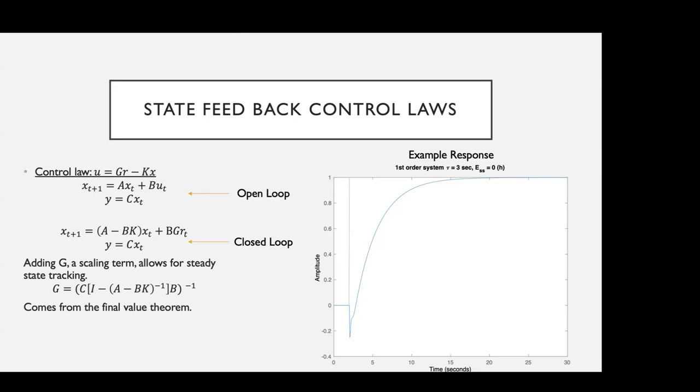If you choose a pole placement, that characterizes overshoot, response time, settling time. There are all those things that you can design for. So if I say, I want it to respond in 10 seconds and have an overshoot of less than 2%, there are formulas to calculate what the pole should be to enforce that. So that's kind of like performance characteristics, I guess. I don't know if that's to the degree that you like.